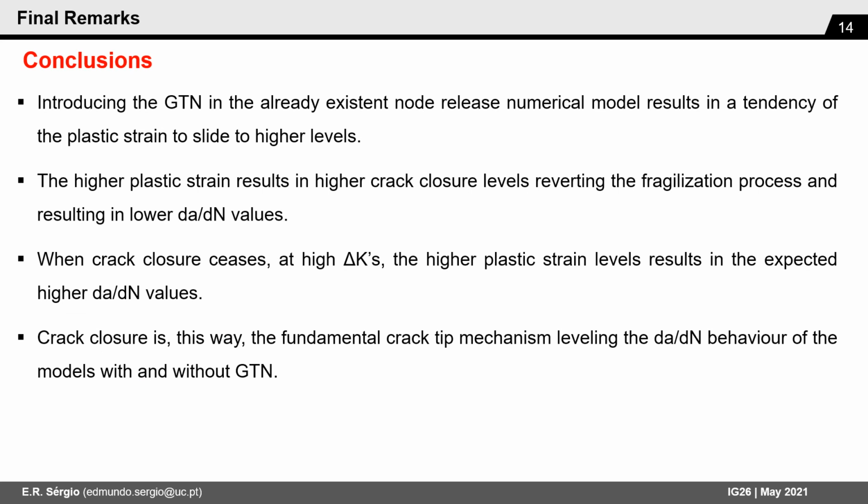This study allows us to conclude that the introduction of the GTN damage model on the previous node-release numerical model results in a tendency of the plastic strain to slide to higher levels. However, these higher levels of plastic strain result in higher plastic wake and more plasticity-induced crack closure, which protects the material, reverting the fragilization trend induced by the GTN.